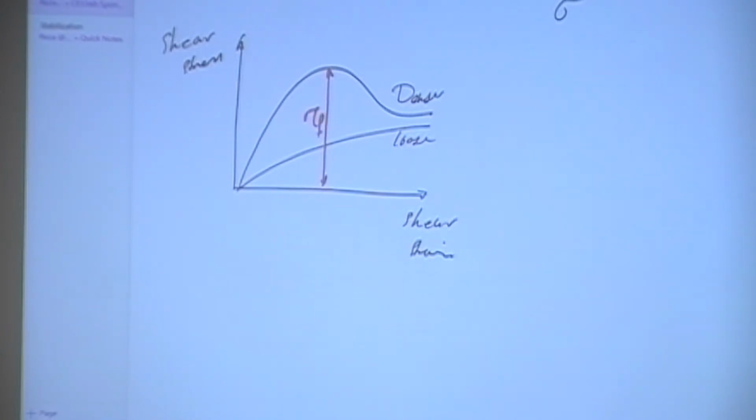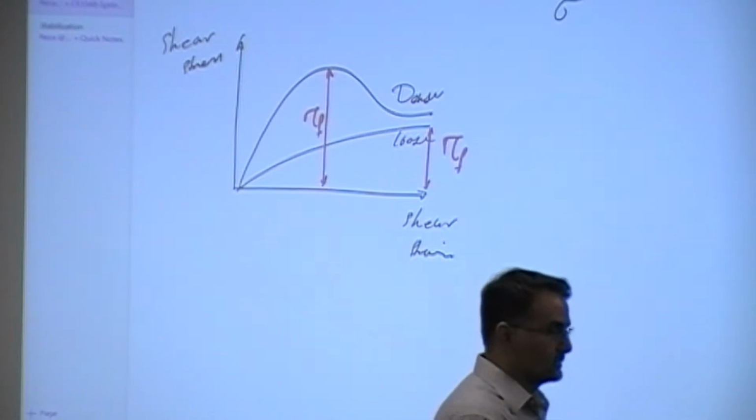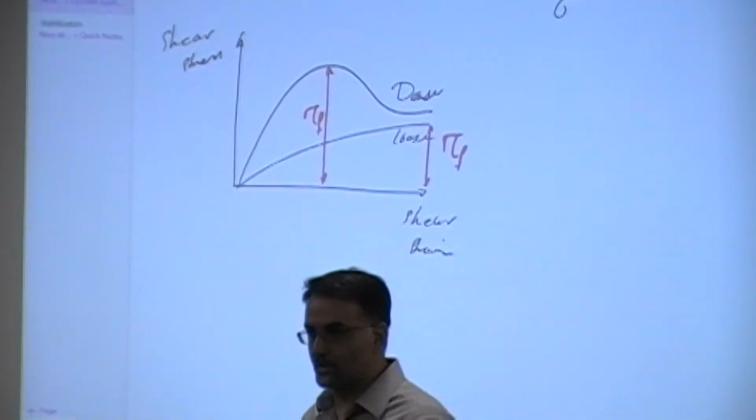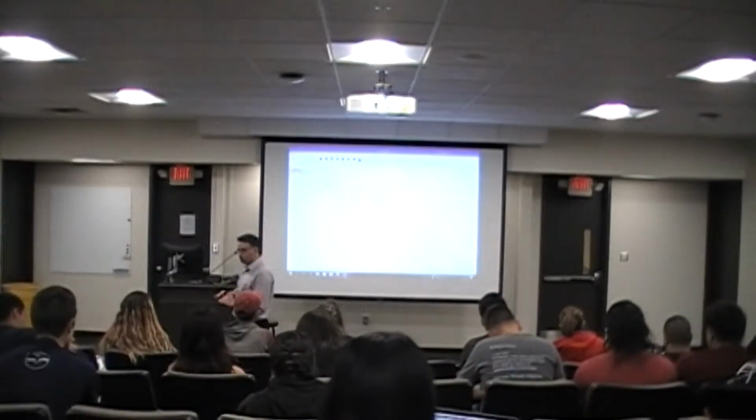And we call this one tau sub F. Alright, so what do I have here? I have shear stresses versus shear strain of the material here. Where do I get the stresses? Based on the stress calculations that we talked about. Remember, we talked about the different types of loads that we have in geotechnical engineering or in general in civil engineering. We had the geostatic stresses, that has to do with the weight of the layers. And then what else do we have? External loads, that has to do with the weight of the structure or anything that is pressing the point, right?